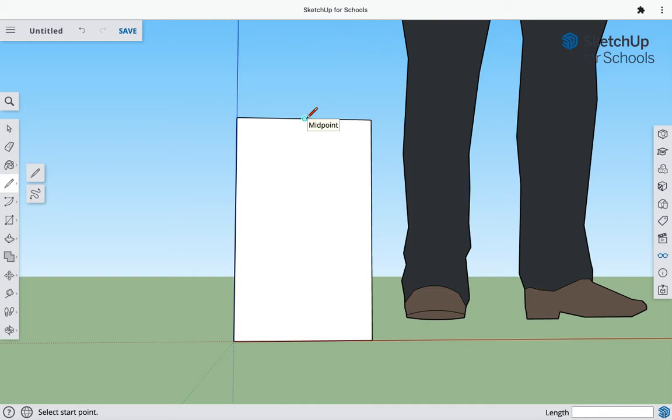Now we're going to follow the same steps. Okay, we selected our tool. Now we're going to click one time, and that's a click and release. We're not dragging. We hardly ever drag in SketchUp. Then we're going to bring our pointer over here, and you see it turns red. I want you to slowly move down until you see that purple magenta colored line right there. So what we did was we selected our tool, we clicked and released, then we moved our pointer where we wanted it to go. Now we don't have a dimension to type in, but we will go ahead and make our second click. The last step of the process is to either press enter or to make your second click.